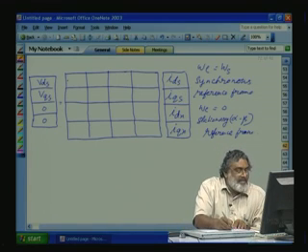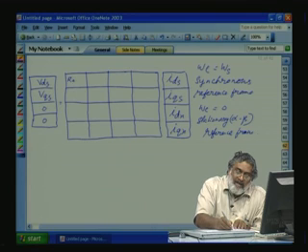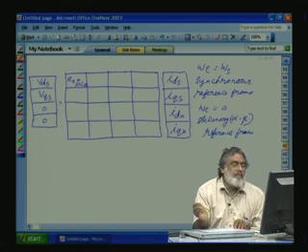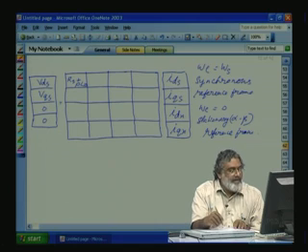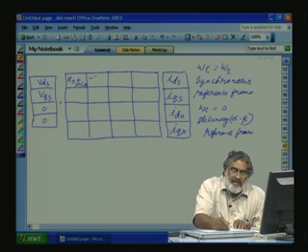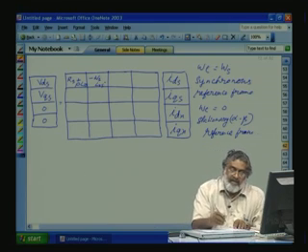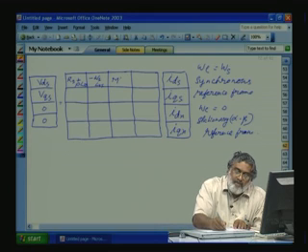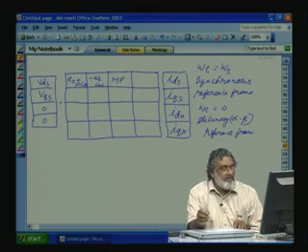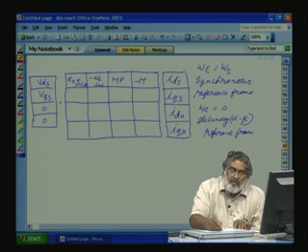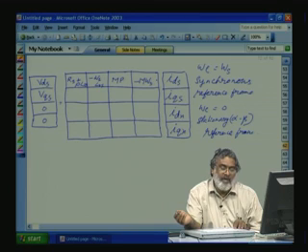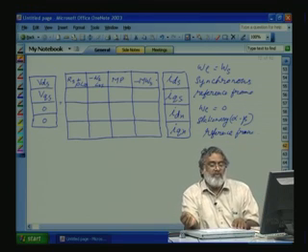So, VDS, the first term, RS plus d by dt of LSS. D by dt we will say P LSS. P is an operator, P is equal to d by dt. Then this one will be minus omega s LSS. The term here will be m into P, where P is d by dt. Then minus m omega s. Okay? That is the stator D voltages.